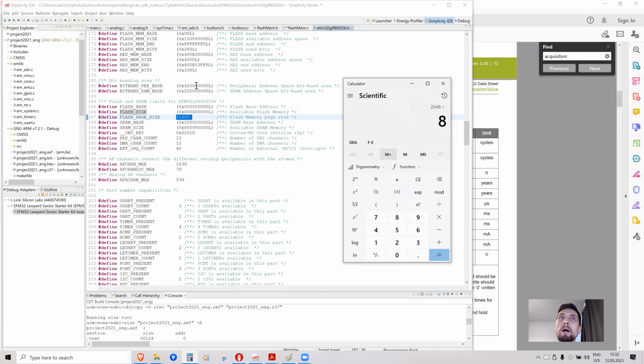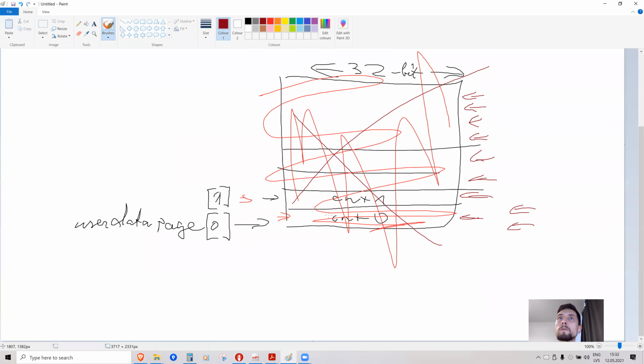divided by 8 bytes for two counters, each having 4 bytes. You could write 256 times into the flash memory and only then erase, if you implemented some kind of algorithm where you only write until the flash page is full and only then erase.